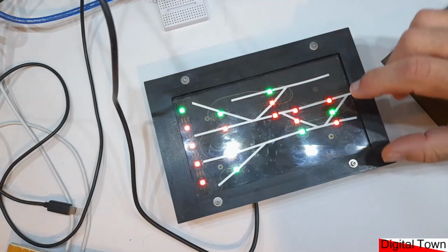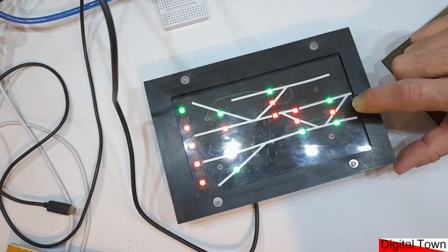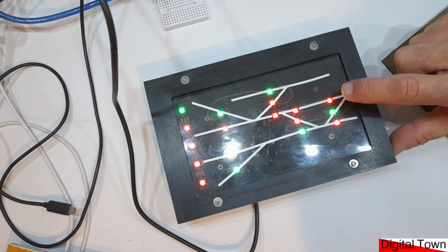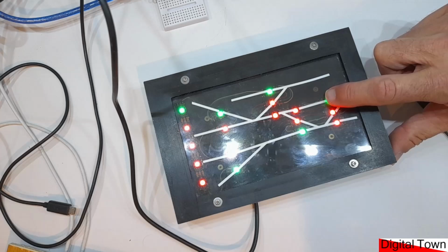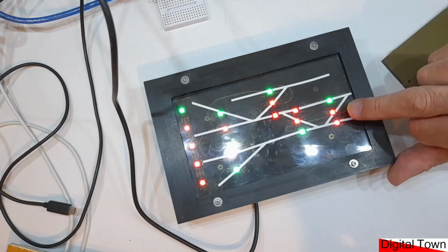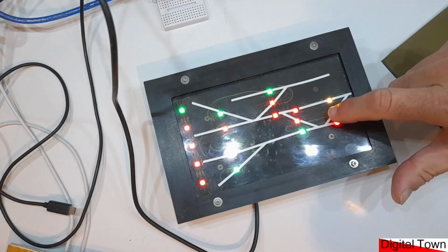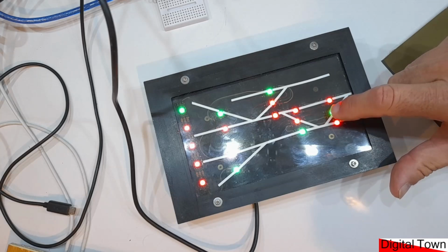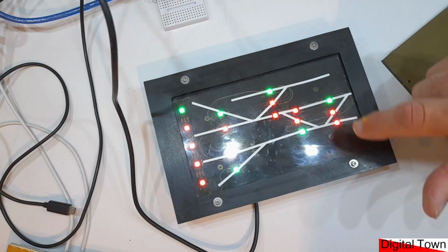Again, I've got that situation where you have a turnout here, a turnout here. If I press the center one, the outer ones both go to red. If I press the edge one, this point both goes to red. I've always done it that way because it gives me a warning that I am not sure at this point what this turnout will do. It will still be turning towards the center, but obviously the track at the other end is not available, so it goes red on both outputs.